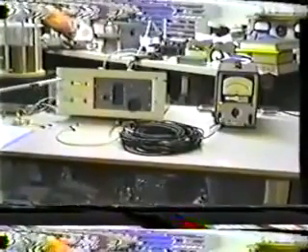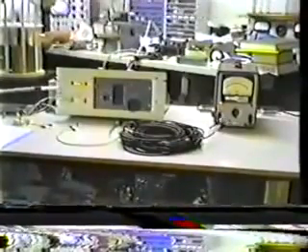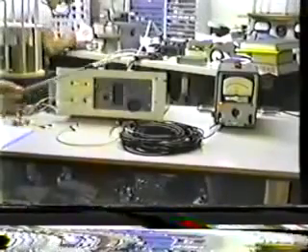The oscillator has gone through another 180 degrees of shift and is producing a right side up impulse to match the reflected inverted, or now right side up, impulse. And this process keeps on going on and on until the voltage rises to a level where the losses of the system prevent any further increase. So what we're going to do is sweep the frequency here and find the resonance point of this cable to determine propagating velocity.